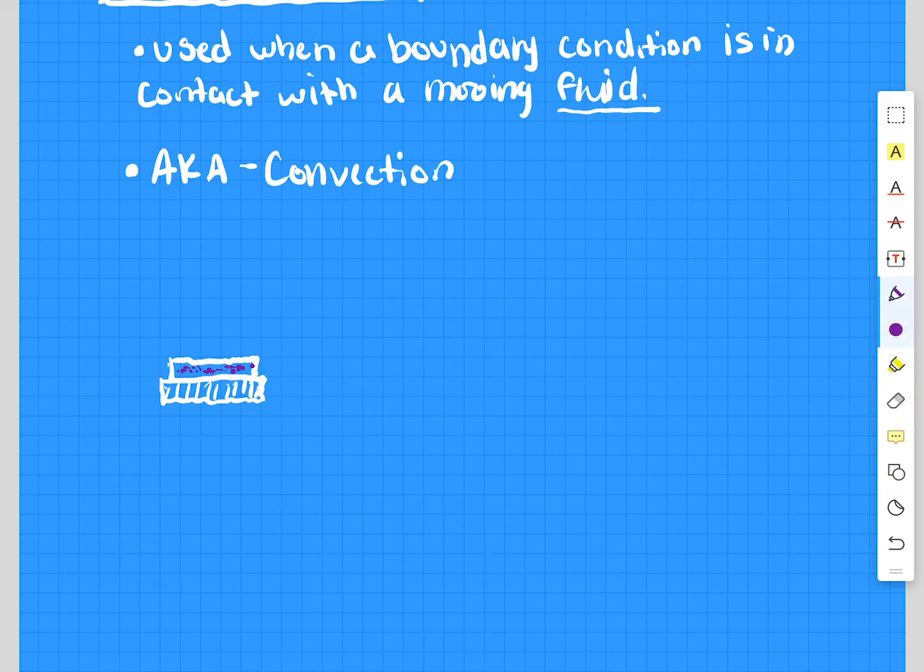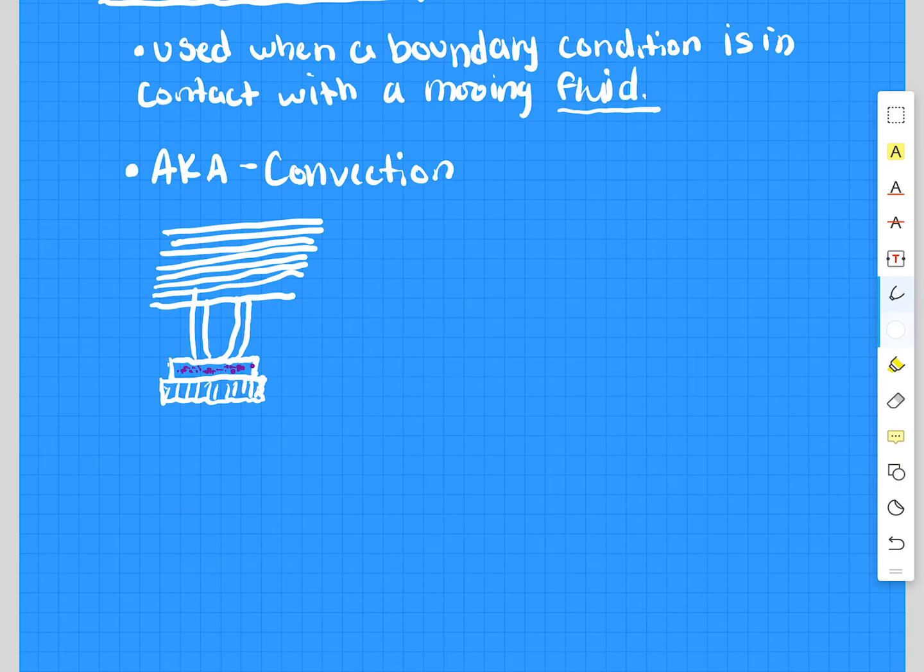That's then usually attached to something else, typically some heat pipes that often end up going to a radiator. So again, we see that the source of the heat is here. Typically, the copper shim helps to conduct a lot more of that heat than it would if we just placed the cooler directly on the processor itself.